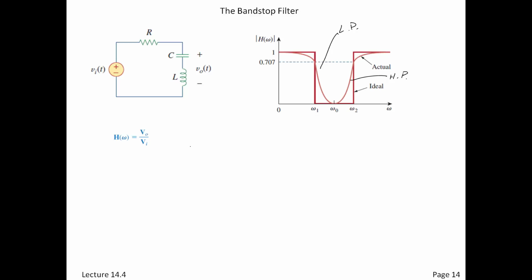All right. Transfer function time. So here it is. Let's get our V0 over Vi. And if we do the voltage divider approach, what have we got? Here's our imaginary terms, no problem. And then here's the sum of them, the real and the imaginary. So now we're left to deal with the same thing. What is the point at which this becomes our omega 0? What omega is going to cause this to have a corner? Square root of LC.